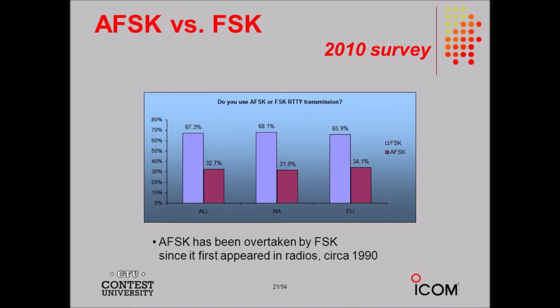Alternatively, we could get a stronger signal for a given amount of RF power. We could also reduce the signal bandwidth to a little less than half that of an AM signal modulated with the same data. The resulting spectrum savings would allow us to fit more than twice as many signals into a space range or band of frequencies.